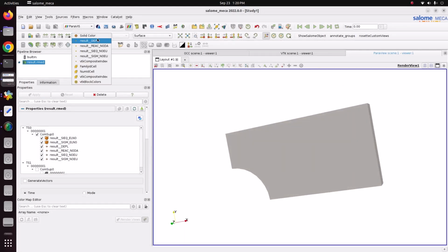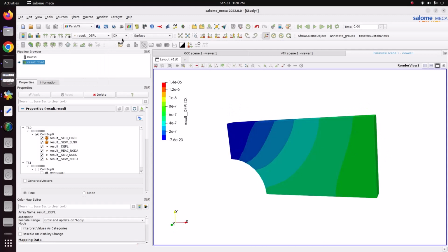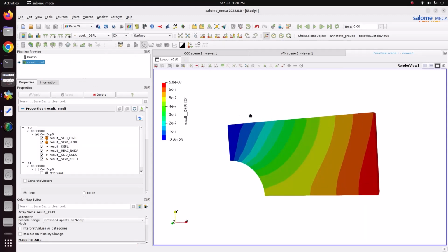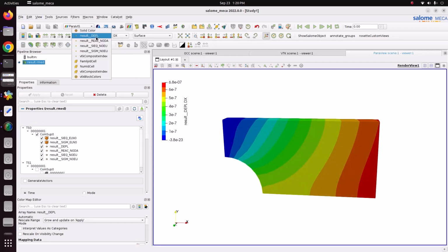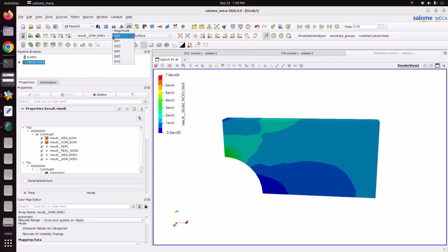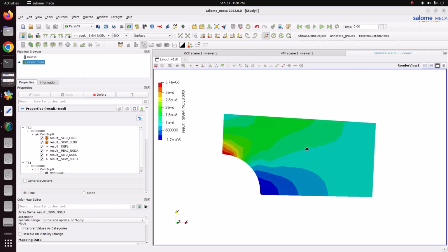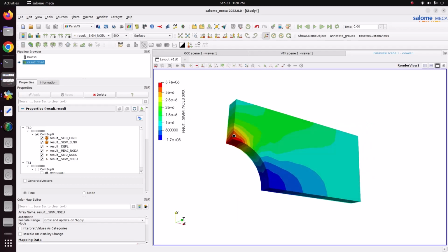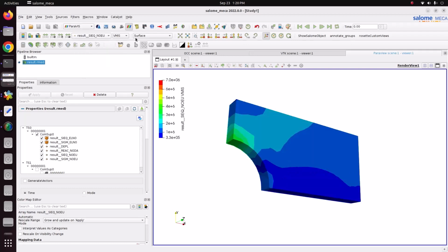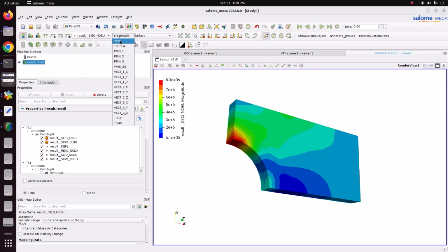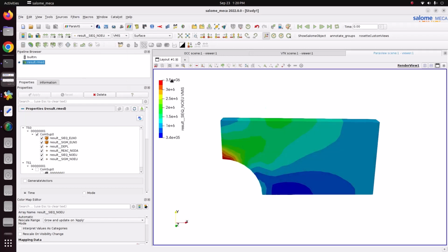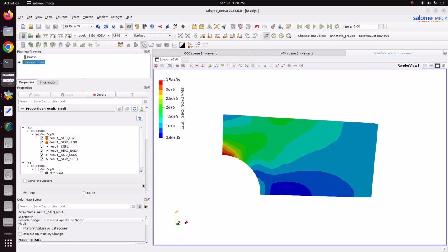We have modeled it. Go to displacement. Here check with the dx. Now again go here, sigma, so here you can check the same stress. The stress whatever we are applying here is 1e⁴. Whatever stress we are getting is almost 3 times more than the applied stress. That is because of stress concentration around the circle. Similarly, we can check the von Mises stresses. So this is also the same, similarly around 3 times more.